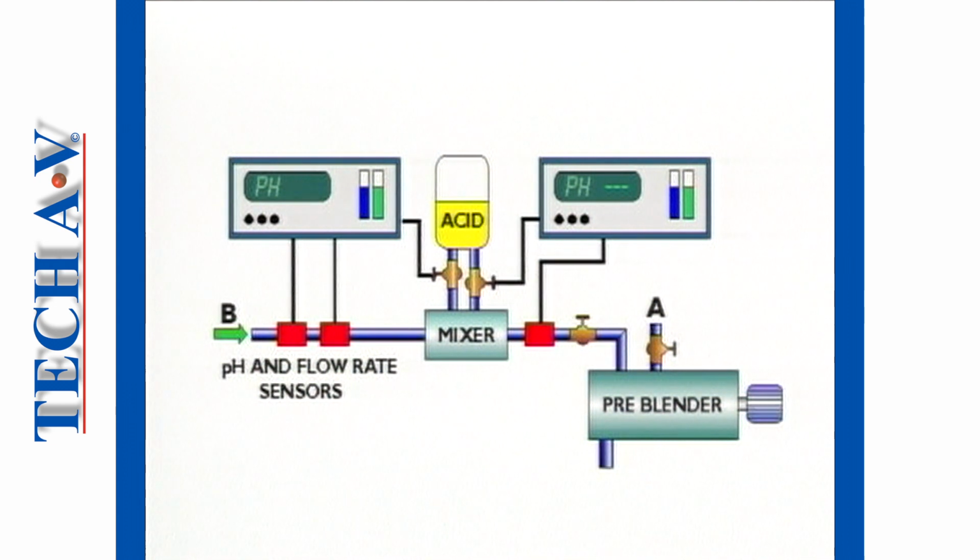Based on flow and pH, the feed-forward controller adds the right amount of acid to component B to bring the variable pH to the desired level. Should the pH be incorrect after feed-forward action has been applied, the downstream sensor and adaptive controller forming the new feedback loop will detect the pH error and add additional acid to compensate.